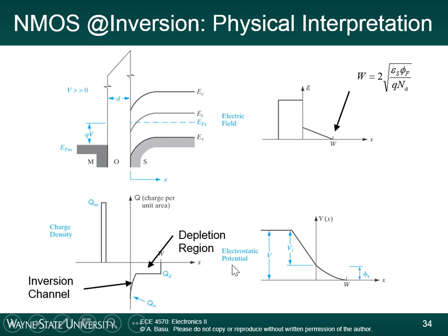Now the electric field drops suddenly because, if we're integrating everything to the left of some point x, first we had all this positive area, and now we have all this negative area that's also included. So if we're here, right where my mouse clicker is, we have this area here, and we also have some negative area that we have to include. The sum of those things is going to bring the total electric field down from this high value. As we continue all the way to here, the depletion charge is also going to bring down the electric field further until it gets to 0 by the time we get to the edge of the depletion region.